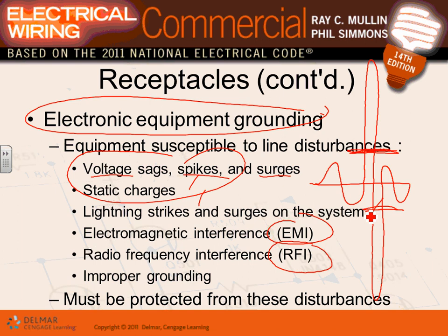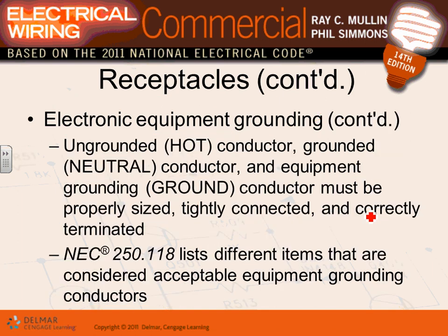Back to the project that you guys are going to be doing. We're going to be laying out quads in a few seconds. Your quads are called technology quads. They are required by the electrical specification narrative to have two things: an isolated ground receptacle and an insulated grounding conductor, as well as a separate neutral. This is just for all receptacles, not just the electronic equipment, guys.